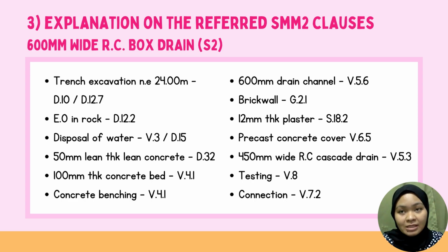Brickwork is taken from section G, which is the brickwork and blockwork. It is taken from G.2.1, which states that brickwork and blockwork shall be measured as the mean length by average height. Fairface and facework shall be measured on the exposed face.